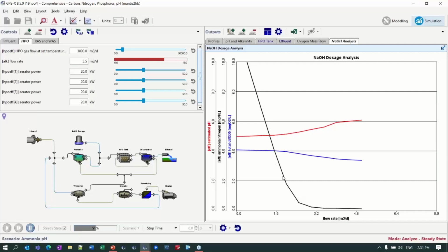So this kind of an interesting analysis is something that we really like to do all the time, to be able to play around with the relationship between effluent quality and one of the operational or design parameters in the model, and do this sort of one-dimensional step analysis. So this is something that's interesting. You may be able to then get a feeling for where you would want to go. And my earlier caveats about the fact this is a steady state analysis still apply here because, you know, you wouldn't want to go right here because there's no wiggle room. There's no safety factor yet in here or anything like that.